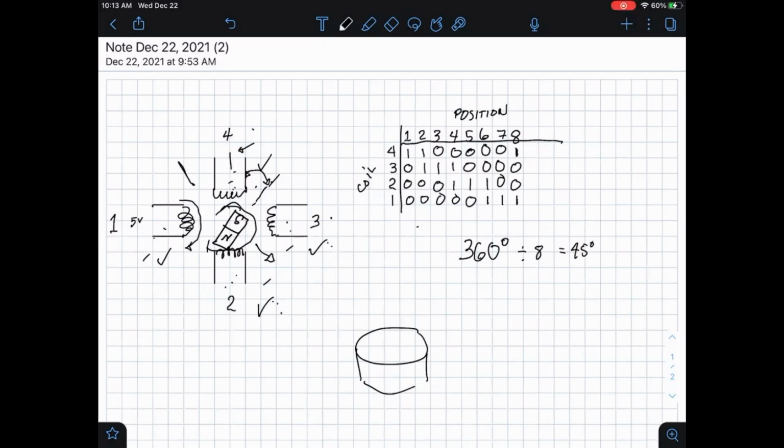So what is inside the stepper motor to improve the resolution of the angle displacement? Well, sa totoo lang, if you break open the stepper motor, so the stepper motor that we have, the shaft is here. Actually, kung titignan niyo yung stepper motor natin, there are actually several gears that are attached to it. Okay? So these gears offer a gear reduction, kumbaga. So a full rotation of one gear or a single rotation of one gear would create a cascade towards the other gears, but will produce a smaller rotation in the final gear.